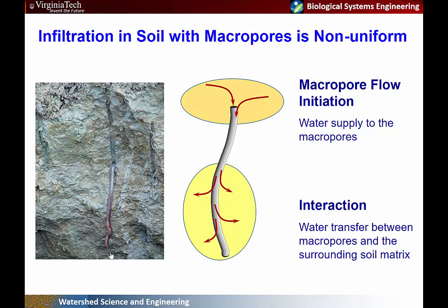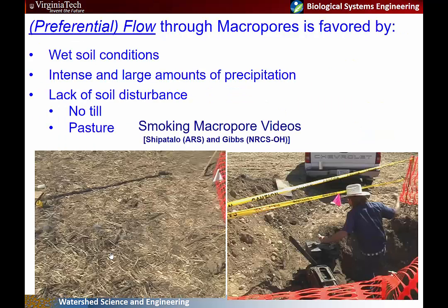This has recently become a big concern in tile drains, no-till tile drain systems. So you get macropore formation over a tile drain. It's not disturbed by tillage. You can get a lot of flow from that soil surface deep into the soil profile, connected directly to tiles. And I'll show an image of that here.